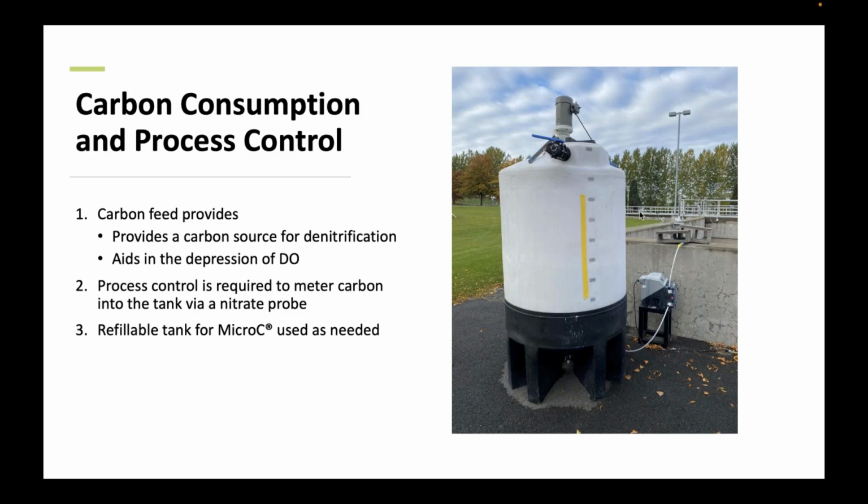We have a big tank like this. It can sit indoors often, and we're actually pumping. We're buying liquid BOD. In this case, it's a product called Micro C, which is actually provided by one of our sister companies, EOSI. They're the leader, I think, in providing that type of product. And you have your metering pump, and you're metering this Micro C into the tank, which is your liquid BOD, and you're controlling that via the use of a dissolved oxygen probe.